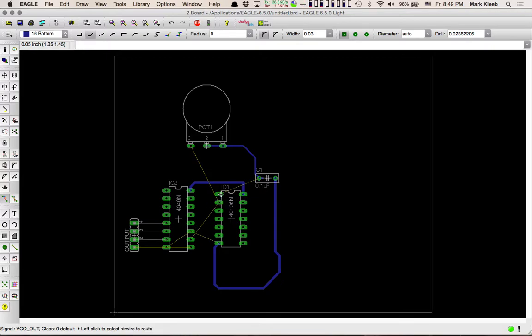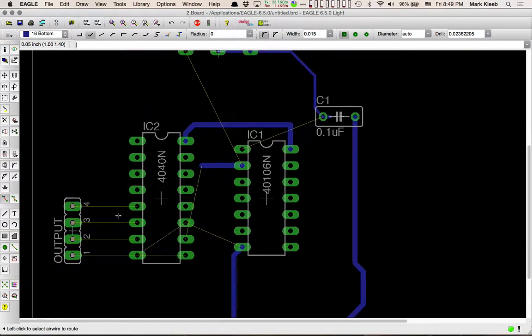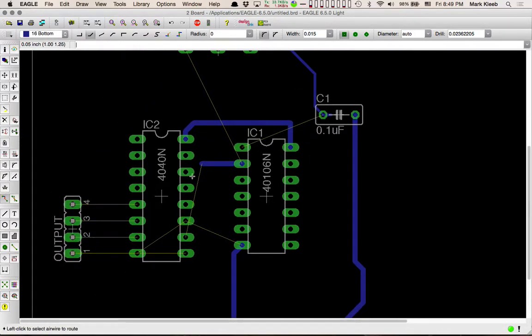This is also a problem. One trick is I can go right up to this chip, and then I can change the width of this to maybe 0.15. And then I could zoom in and maybe go between those pads. Right? Now I can make it big again.